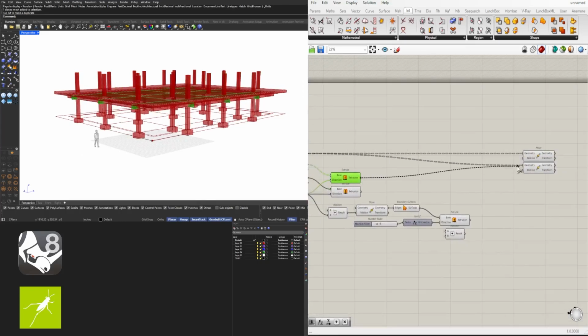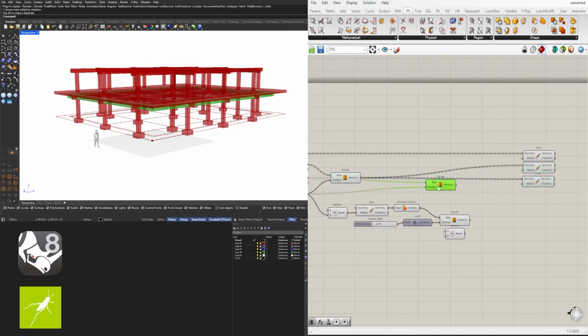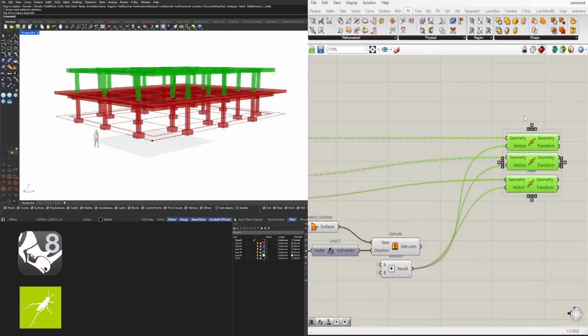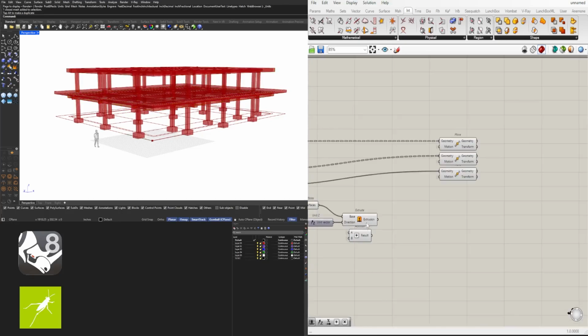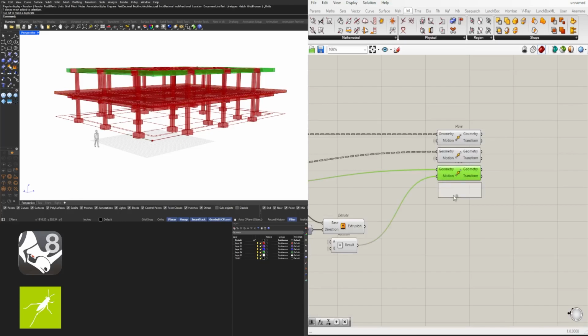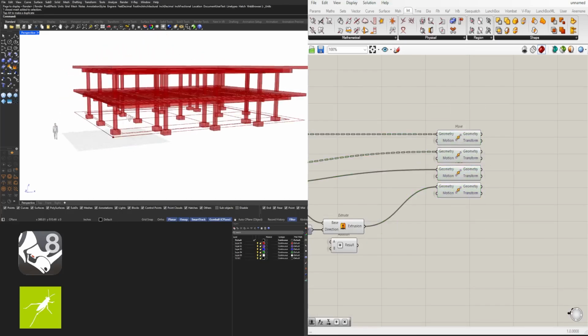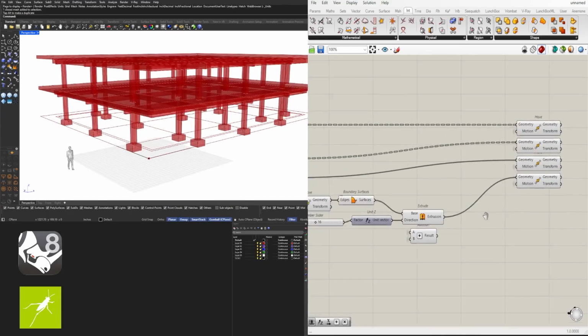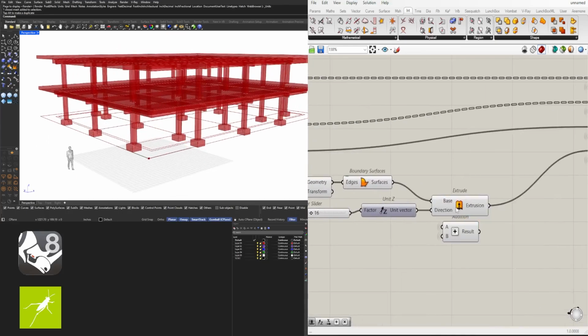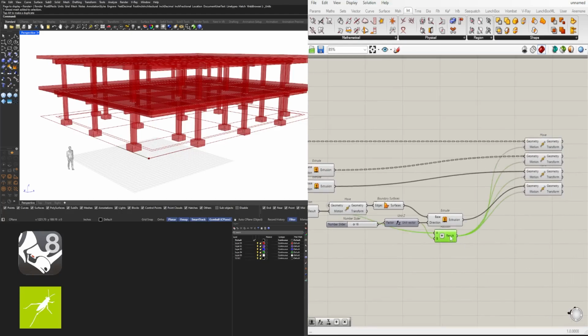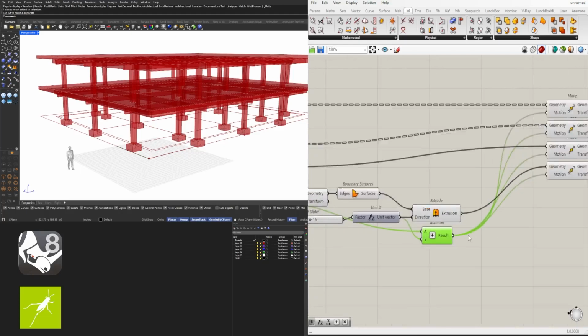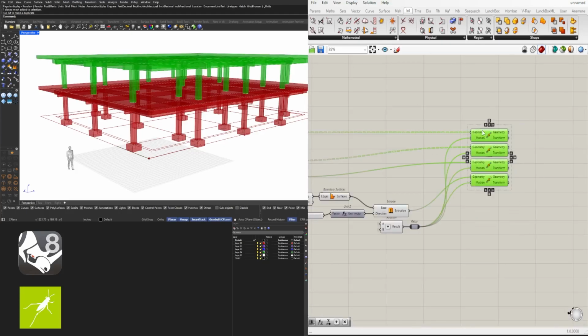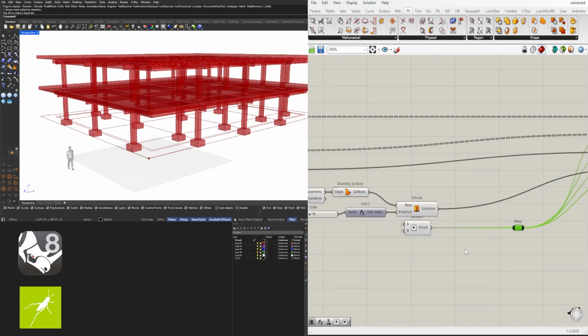The beams. And the floor slab. So now this is a 2-floor. But notice that we only have 2 floors. And the reason for that is because we only added one number here, 160. What we need to do is take 160 and create a series of numbers stepping by that amount.